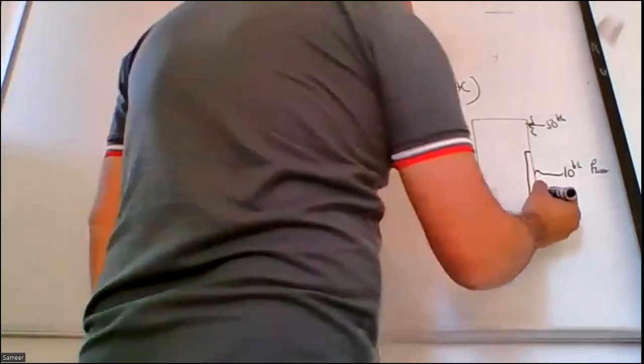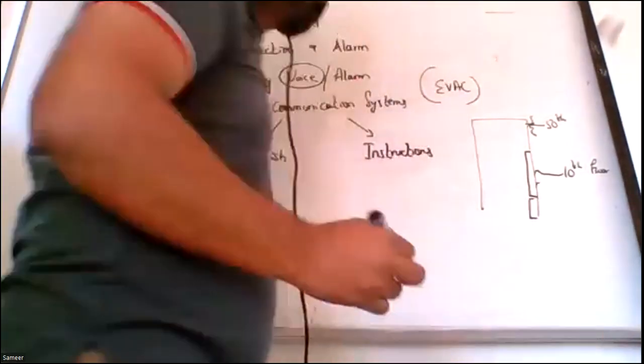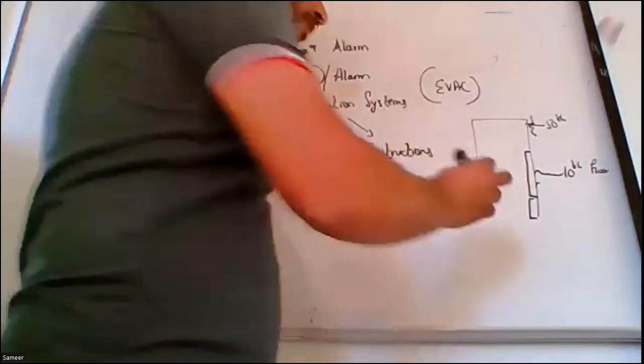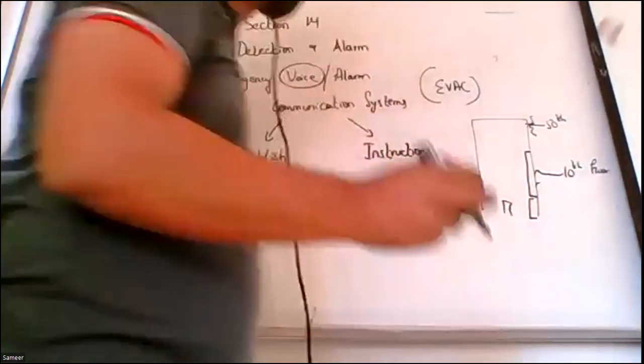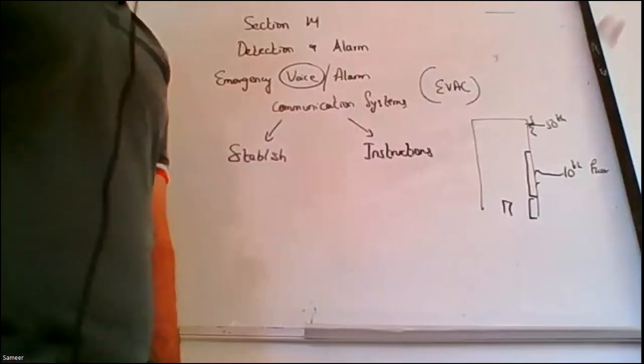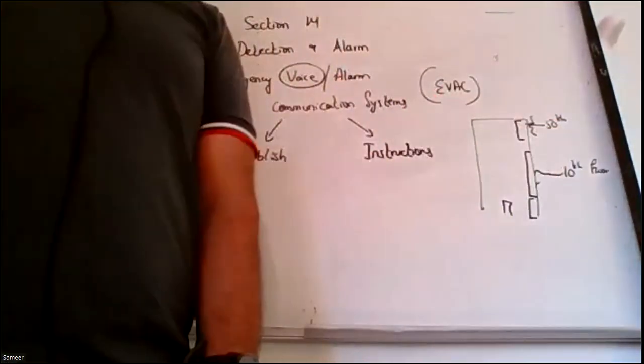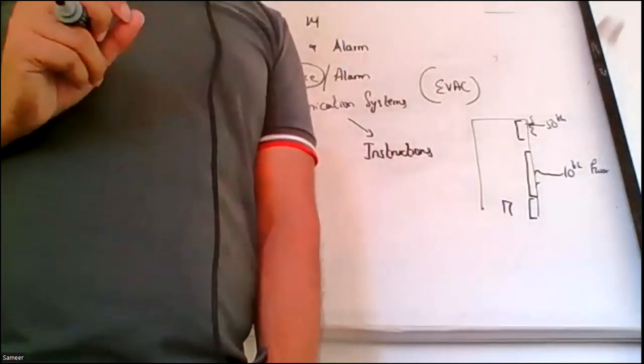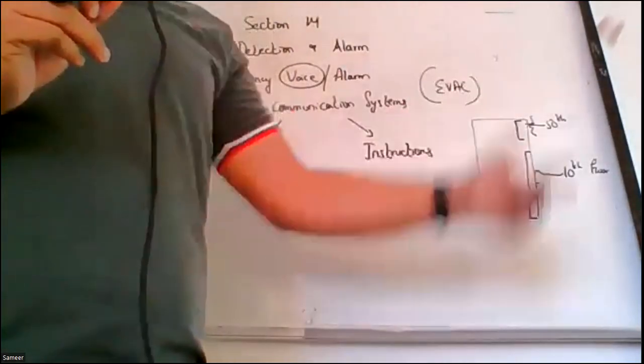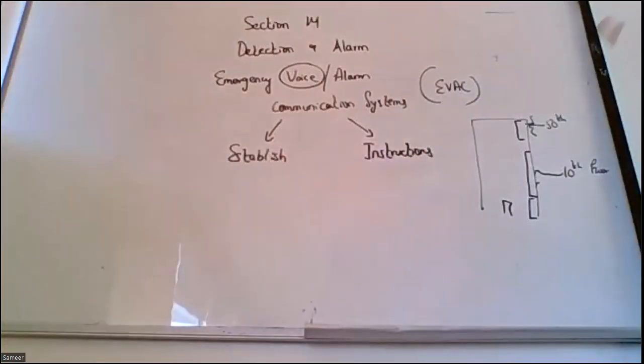People from 1 to 5, please move towards a refuge room, or if you find a safe passageway, exit the building. People from the 49th to the 25th floor, no need to evacuate. Stay in the refuge rooms so that you are not congesting the whole stairways. So you want to give instructions to the occupants so that you can evacuate the people in phases. I'm just talking about a 50-floor building, but we have 150-floor buildings also.